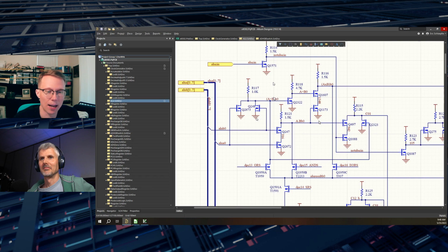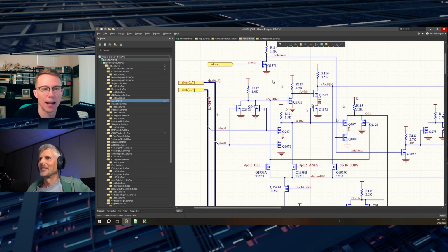And then I had some kind of a timing figure of merit. It's been a little while since I've done it, so I forget which number I used. But maybe it was a microsecond or something like that. So, RC equals 1 microsecond. And then for the specific capacitance, you can calculate the required resistance to target that particular propagation delay. Amazing. So it's all propagation based.